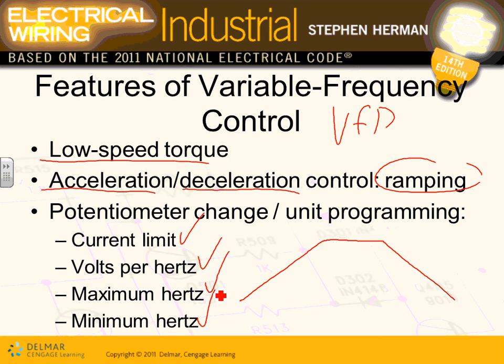Gentlemen, if you are in the electrical industry and you're specifying most of this HVAC equipment right now, when we went to Boston Scientific, did you guys see all the VFDs over there? That's what you're looking at. Why would they use them? They ramp the motor up, and when you turn it off, they ramp it down instead of just up, down. Ramp up, ramp down.